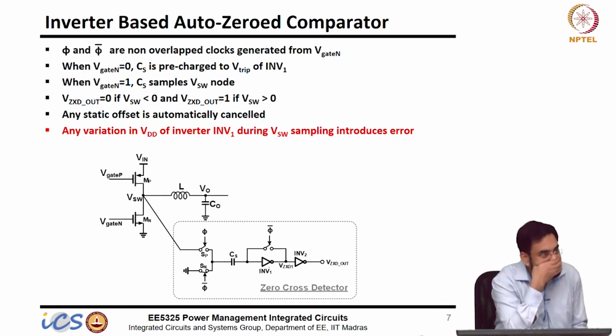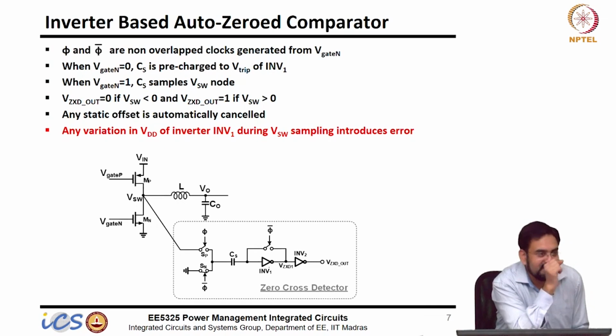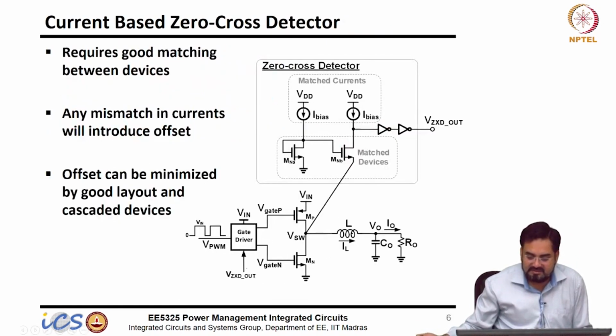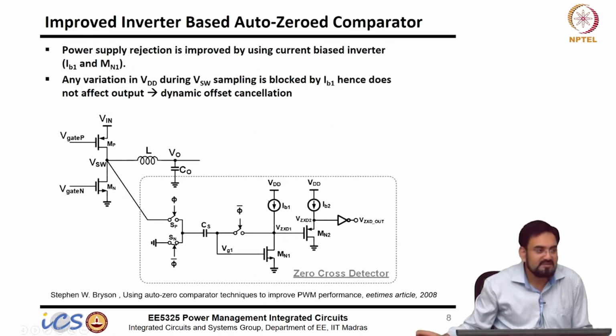You can use the regulated output as its VDD. No, then you need a whole regulator. Just do the small thing, I do not want to put a big regulator there. Think about this: is it sensitive to VDD or not? No, not sensitive. So, just replace the inverter with this ideal current source. But the current source itself is a MOSFET. So, what is the problem with that?